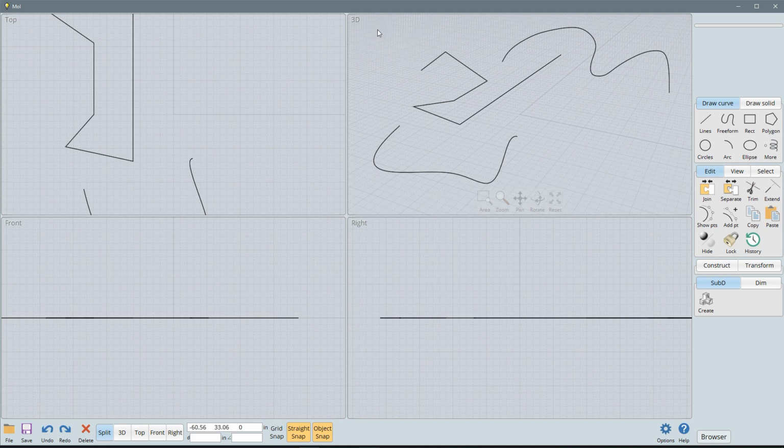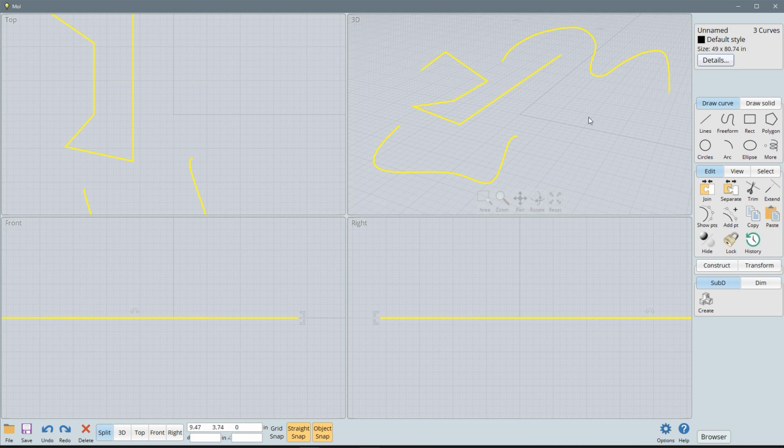And if you drag from the left, either bottom left or upper left, you'll notice it doesn't select anything yet. So you have to surround the entire object before it will be selected. So in this case, I only got the one. So let's deselect. We'll just left click. If you come from the right, it'll get everything it touches. So that's just something important to remember when you're making selections.